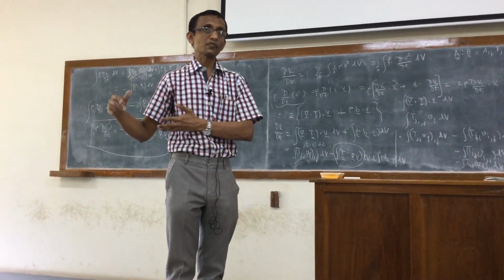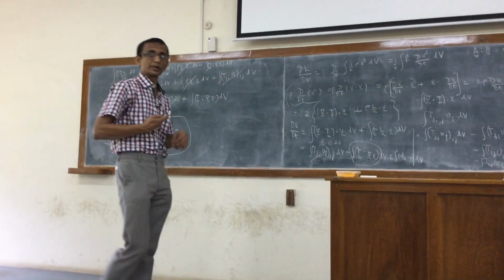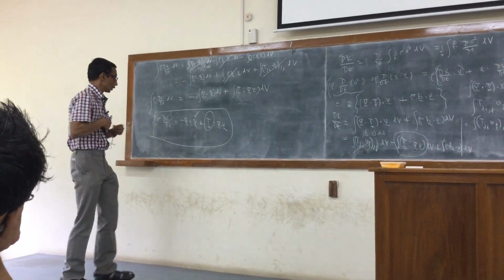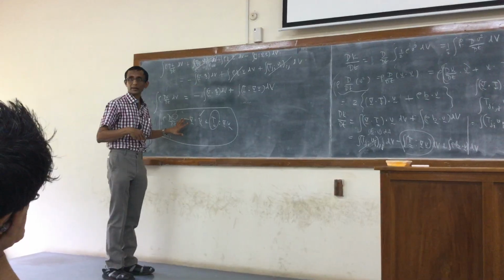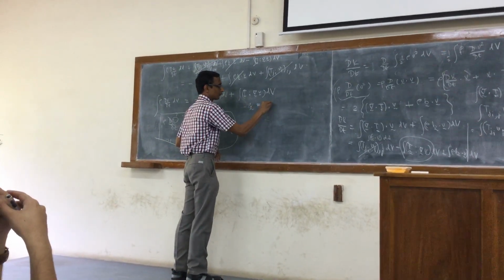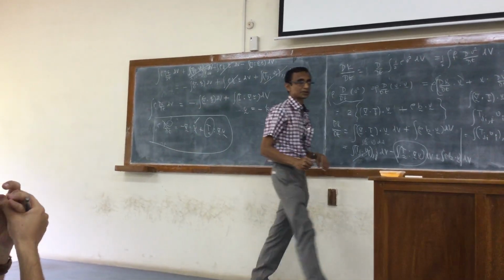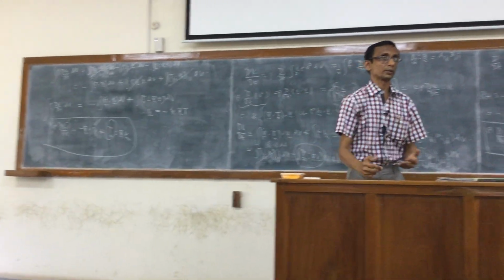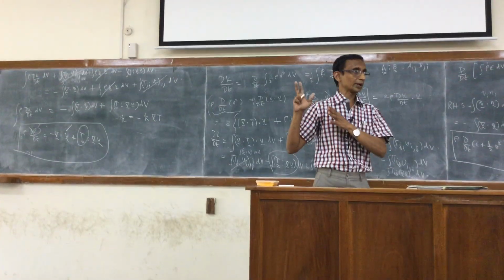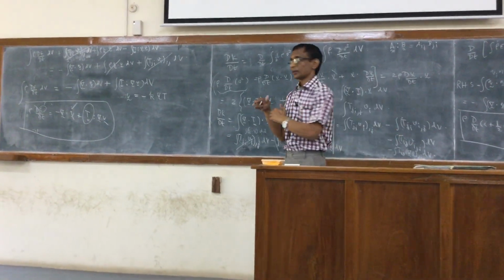So for that we have to specify the particular fluid we are going to consider, and it will make a difference whether we consider a compressible fluid or an incompressible fluid. Now this is of course independent of that, compressible or incompressible. So Q we will take as being given by Fourier's law of heat conduction. This is again a model. Not all bodies will obey it, just as the linearly viscous fluid responds to only a particular class of fluids.